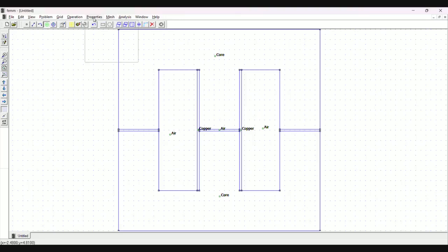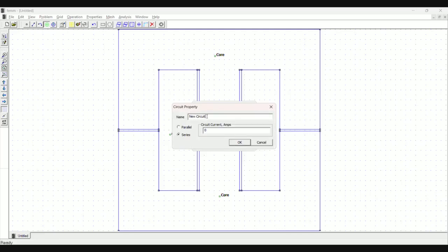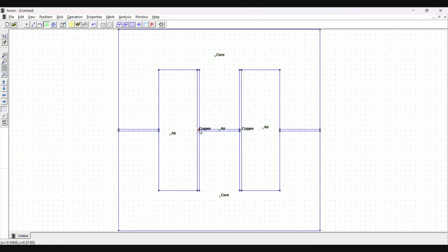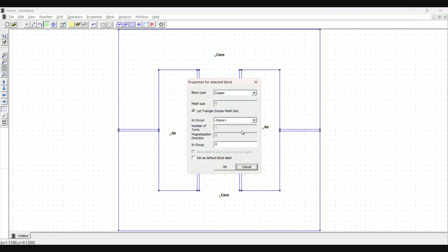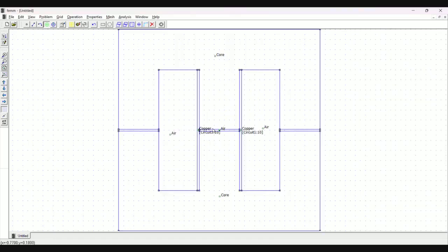So what we'll do, you see here, there is something called circuits. Add property, select, this is your new circuit, so circuit 1, then tell everything is in series. We'll talk about parallel later, you can just explore, we'll not talk about it in this session. So we'll think 10 amperes of current is flowing. So yeah, just select these two and click circuit, select circuit, and see, you can see 10 number of pins. Just assign. But if you see, both are positive.